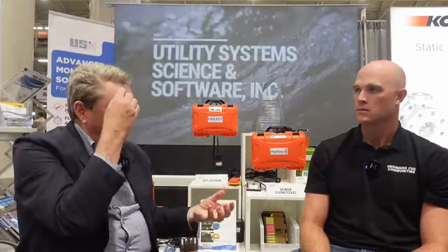We superimpose the AMI data, which is water meter data, with our flow monitoring. I won't say there should be a one-to-one relationship, depending on irrigation, but we'll be able to trend this water consumption data to the dry weather data. And if it's not, then we know where else it's coming from.